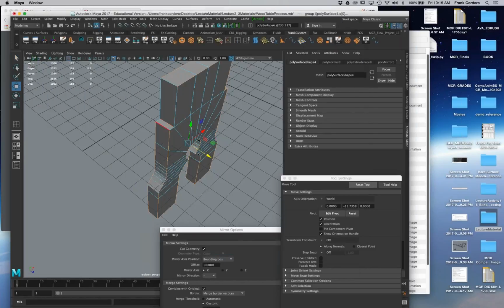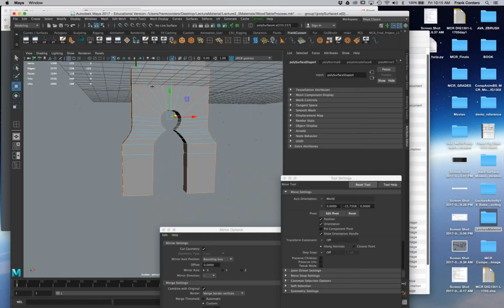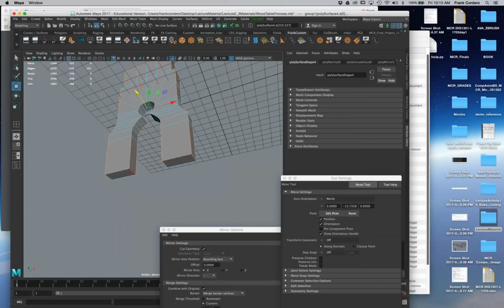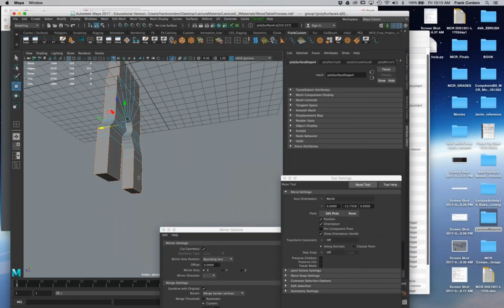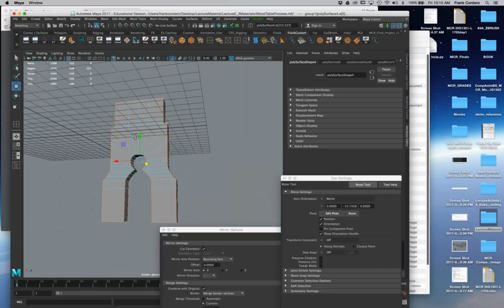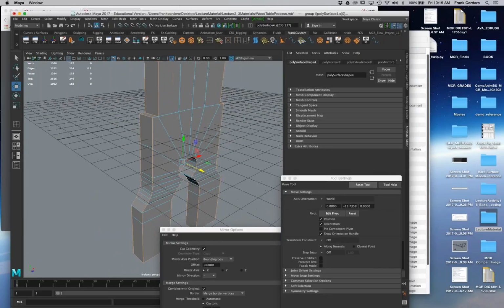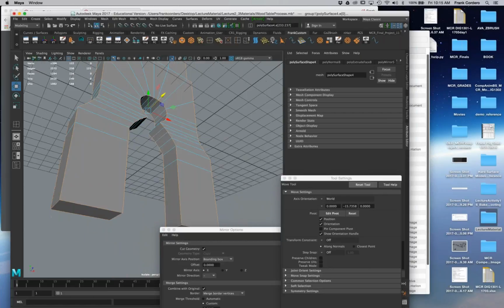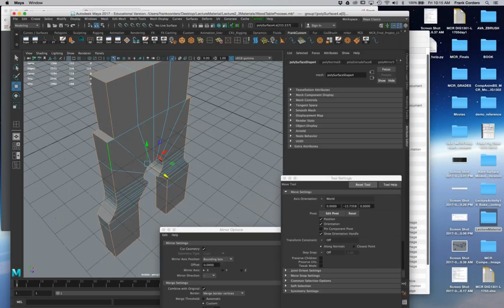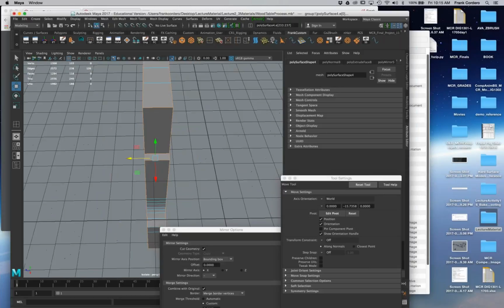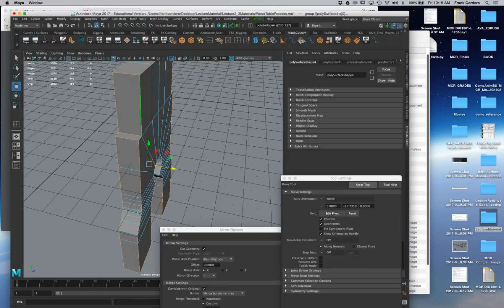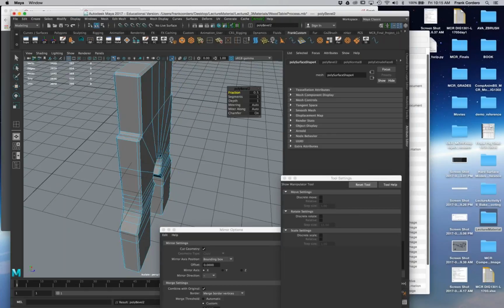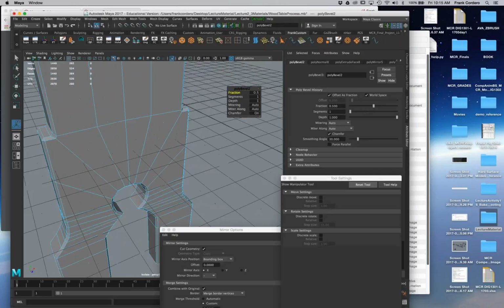All right, I'm going to keep on selecting edges. Oops, I'm missing an edge or two. One here. See, the trick when you're doing bevels is that you want to make sure that you get them all. You don't want to start beveling one side, then miss this area, and then keep on beveling, because then you're going to have to do a lot of cleanup. You usually want to try to hit all the connected bevels that you can. All right. Shift right click, bevel edge. There we go. And now we're going to go ahead and do 2 segments.